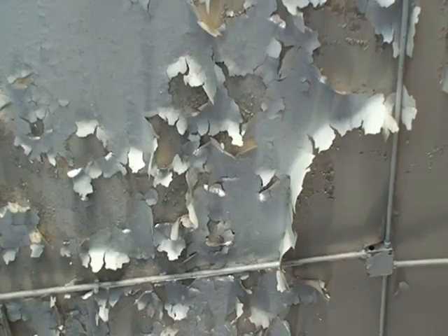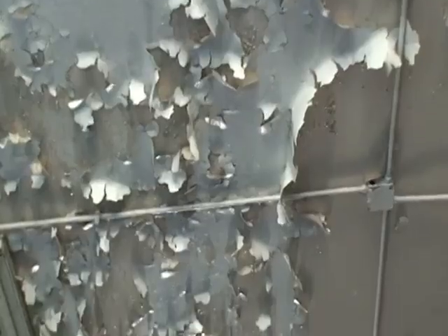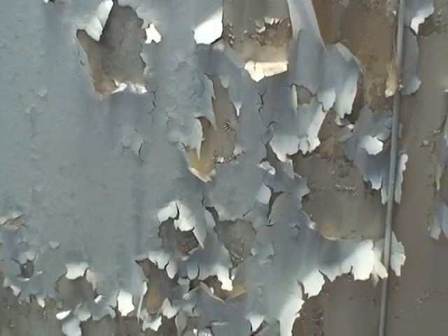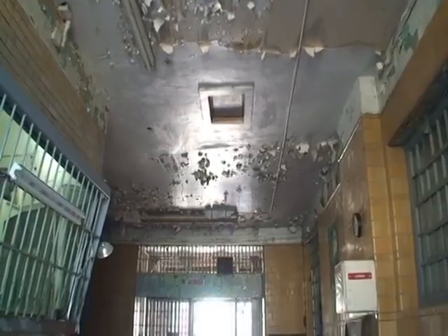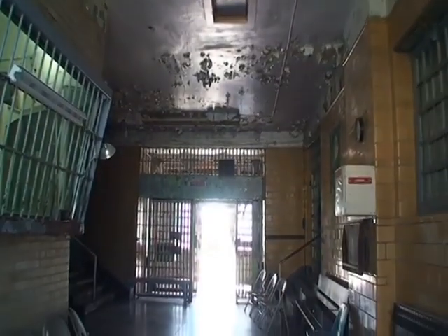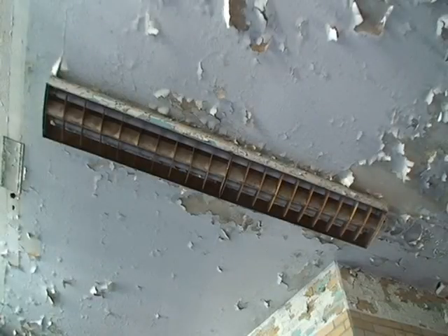If you look at the paint on the ceiling of this building, you'll notice it's starting to alligator and delaminate from the ceiling itself. That's usually a lead-based paint or a paint with a lot of metals content in it. If the building is going to be demolished and the paint's in this bad a condition, they'd have to come in and have some kind of abatement done ahead of time and characterize that paint for RCRA metals and potentially handle it as a hazardous waste. If that paint's actually in good condition and intact, there's no need to do any kind of abatement or removal prior to demolition.